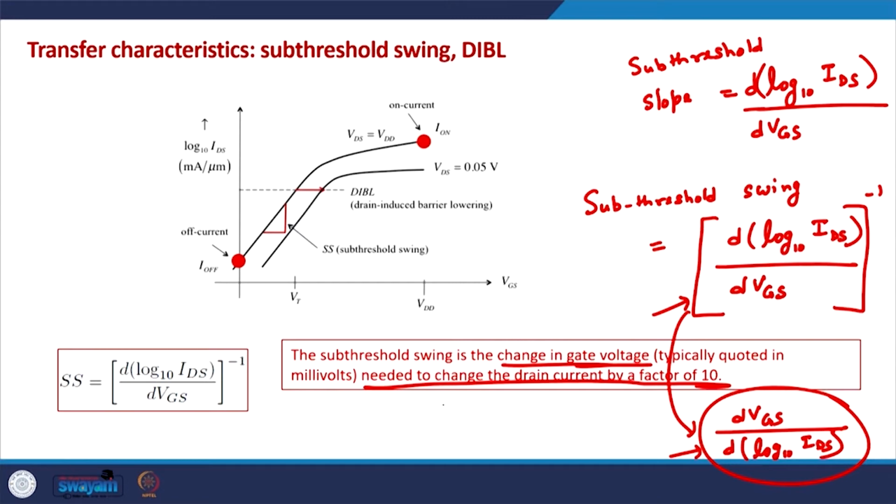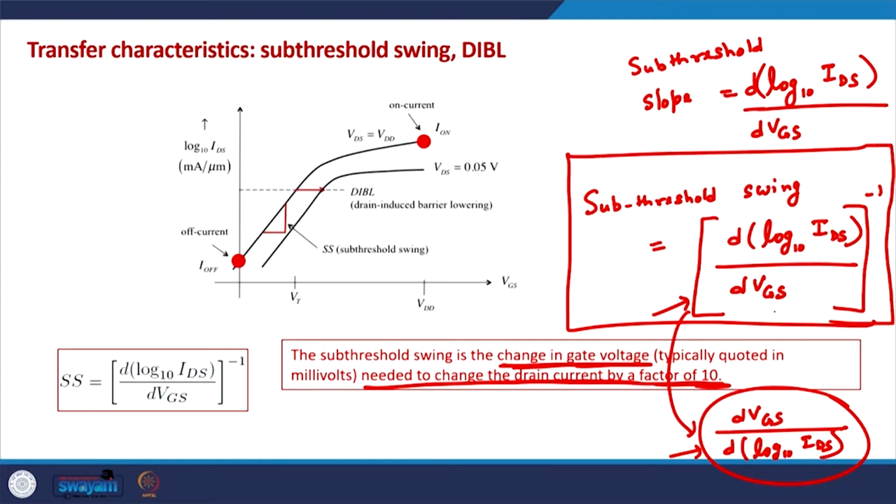And this is defined as the change in the gate voltage below threshold voltage, in the sub-threshold regime, that is required to change the drain current by a factor of 10. That is defined as the sub-threshold swing, and this is an important parameter, especially in devices operating very close to the threshold voltage. In many modern day applications, especially neuromorphic applications, the devices need to be operated very close to the threshold voltage, and in that case the sub-threshold characteristics become extremely relevant.